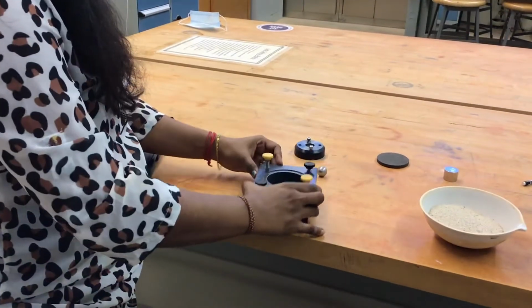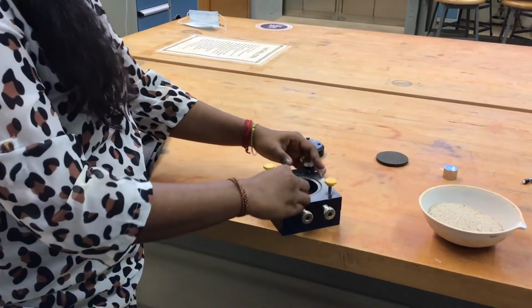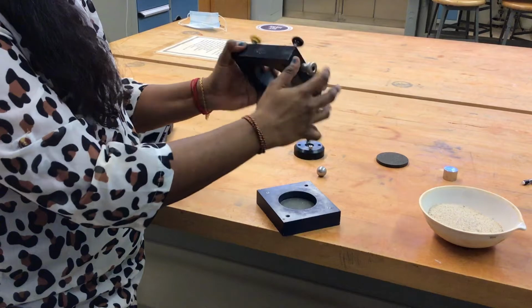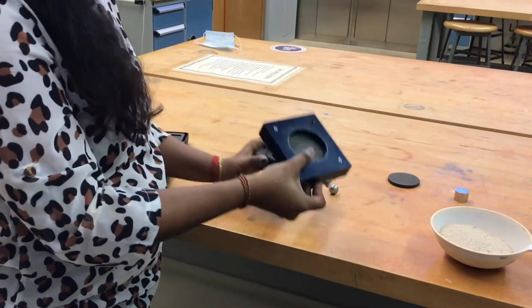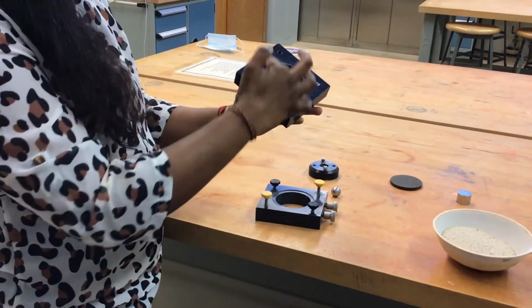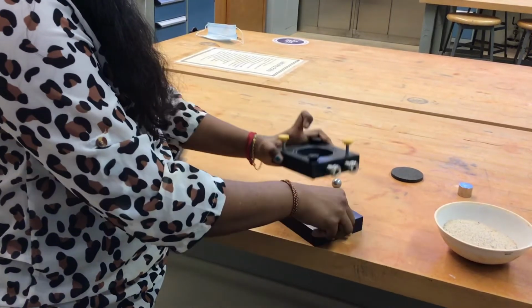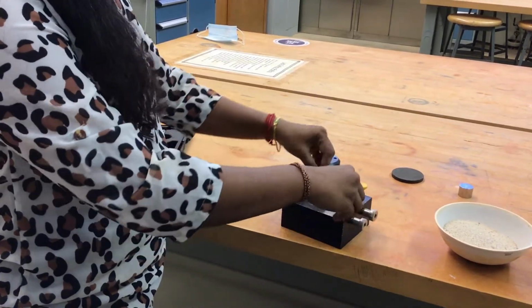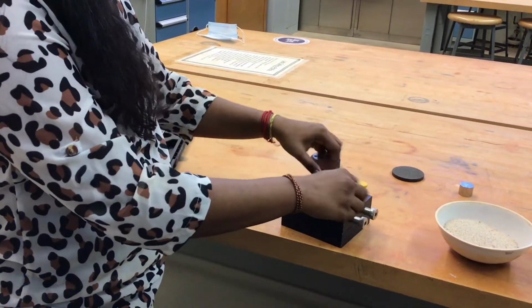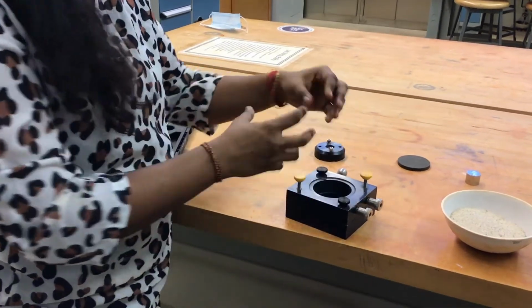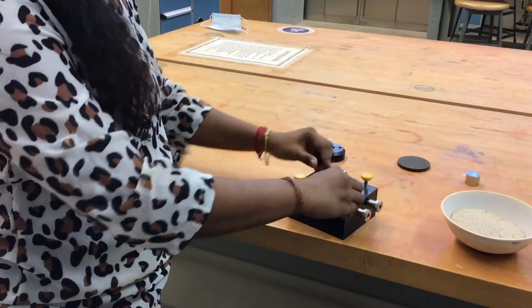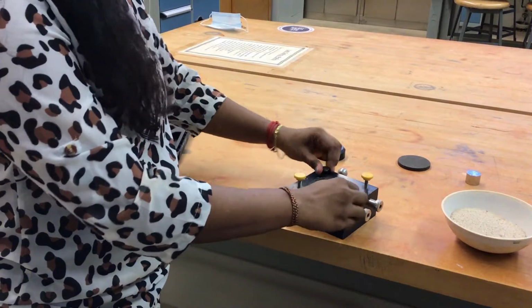So initially what I'm going to do is fit on this one, and there are two rings on this. You can see one with a black and then one with a yellow, and in this bottom you have holes only for the black rings and not for the yellow one. The purpose of the black rings is to hold these two together, and the purpose of the yellow ring is to provide some spacing when you have shearing. So I'll tightly put these black rings.